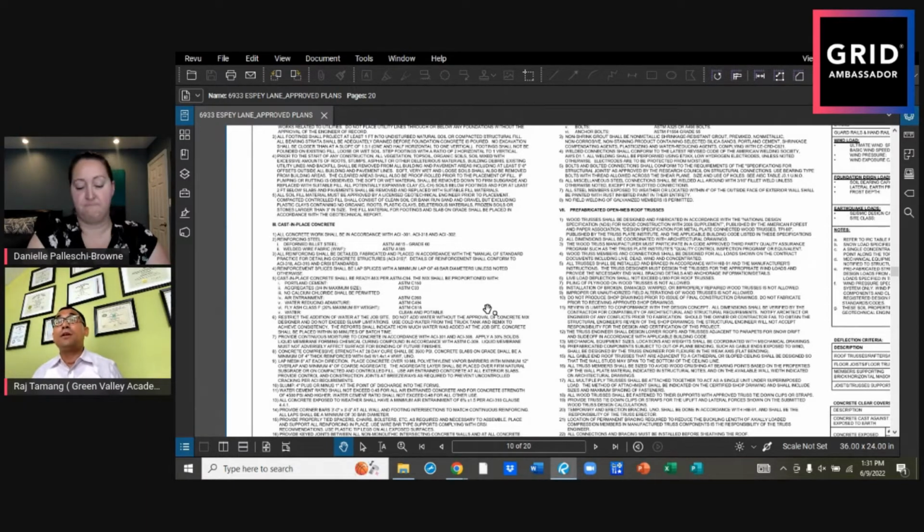If you do a commercial project, a concrete building, an elevated parking garage, it's 5,000, 6,000, 7,000 psi, not 3,500 psi. It's strong concrete and more expensive. Mostly when it's stronger, you're putting in more cement and rebar, because cement is definitely more expensive, right?